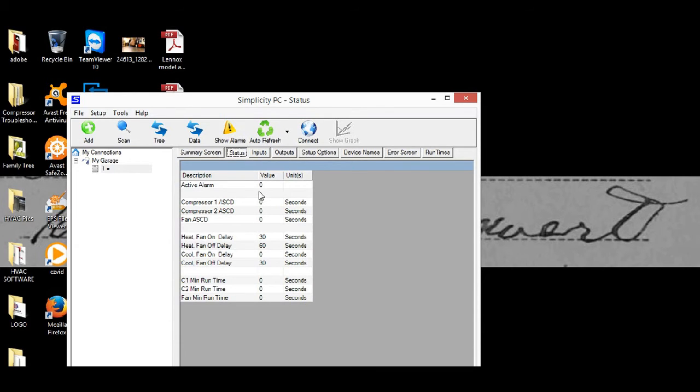Now we're just looking at the board as it was when we first plugged in. It's not refreshing, or we're not watching it live. So we need to come into the auto refresh while we're working on this, and you can choose it to update every so many seconds or in 1 minute, or use a define. We can even make it quicker or longer, but 5 seconds is plenty. You notice now it's going to be monitoring that board. In every 5 second intervals, we're going to see these counting down. Once it reaches 0, it will allow a call for cooling.